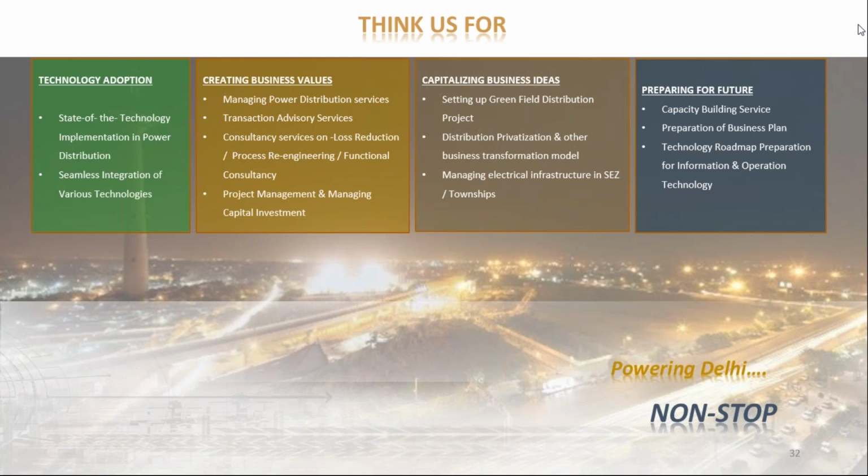I think that depends upon the current capacity you want. There are standard conductors which are specified: for this capacity, this conductor is to be used. In India, we have IS standards, and those IS standards define that. I can have my engineering person send those guidelines on what kind of conductor we are using for what current capacity, and that could be helpful to you.